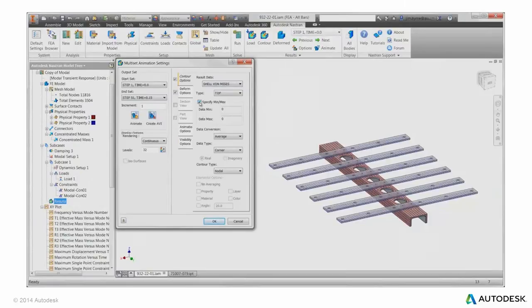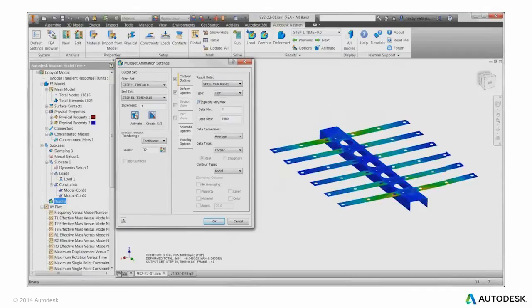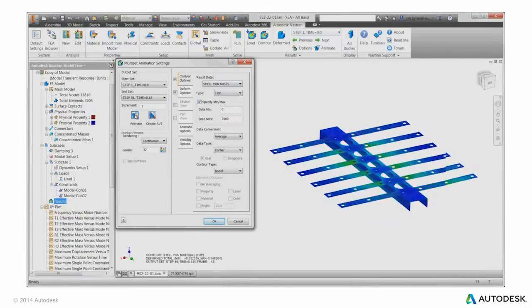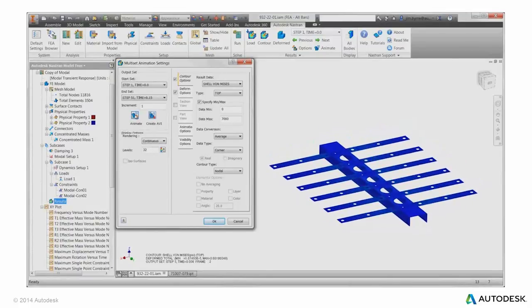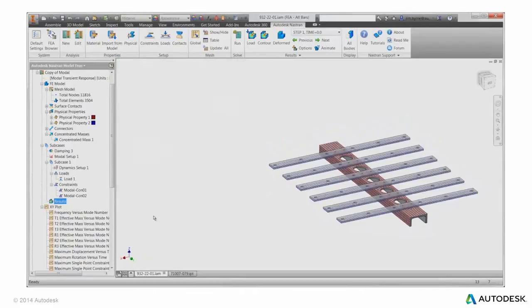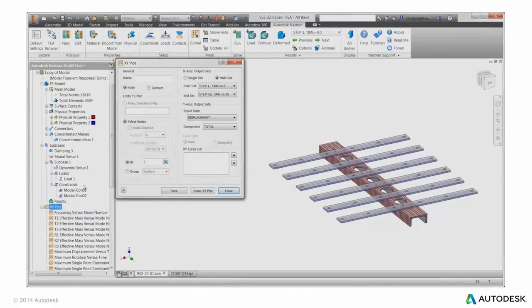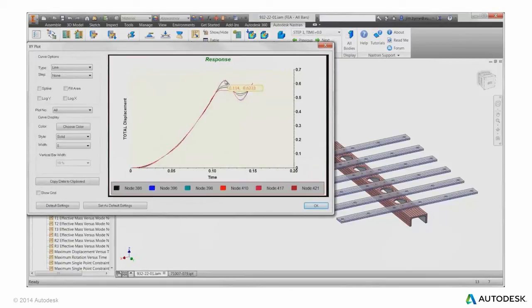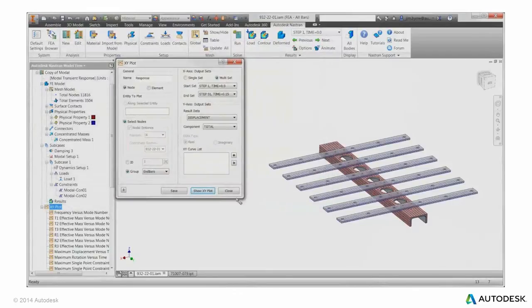We can look at things like stresses, we can look at displacement. We're looking at the stresses here as it's operating. We can see the arms are moving. We can actually interrogate this a bit more. I've taken points or nodes at the end of the arms and am viewing them graphically. Now the units shown are in inches, but this is showing that as the arms go up, they actually deflect back down again by about 3 millimeters, which is excessive. So the cuts are likely to fall off.